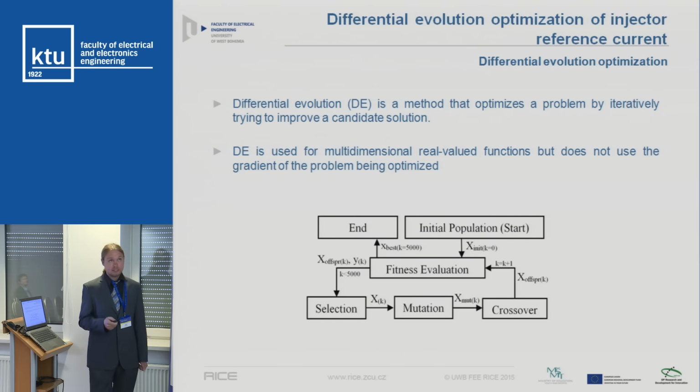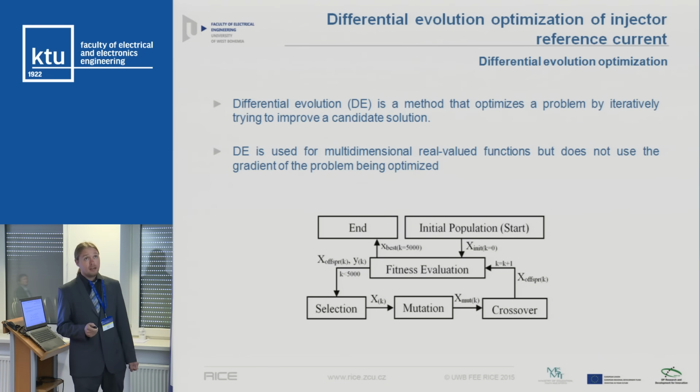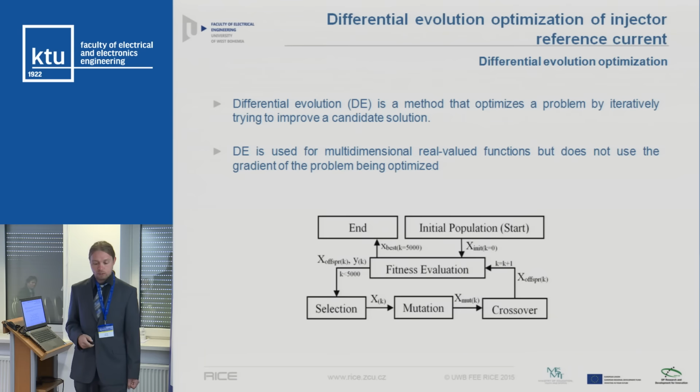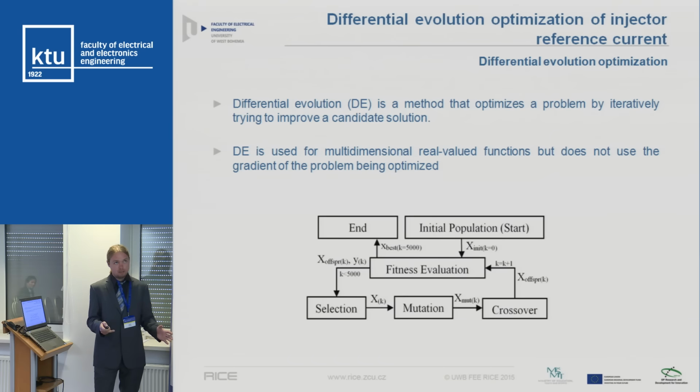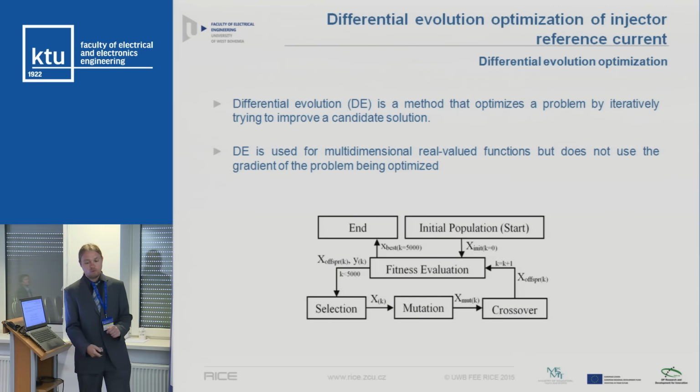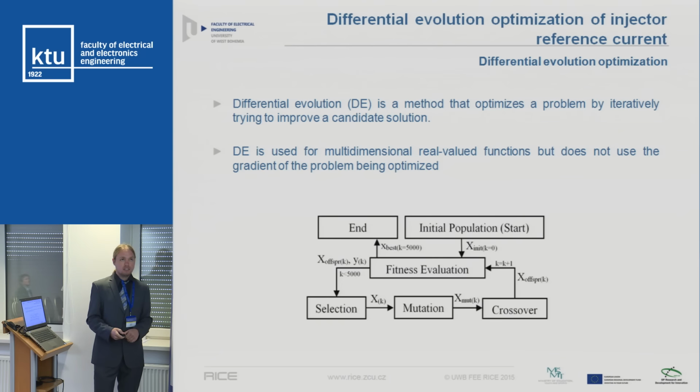So we inject up to 12 harmonics. As I mentioned before, we want to minimize the peak-to-peak current. This is a problem of global optimization in the real space. We are looking for the best phases of these harmonics to achieve minimal peak-to-peak.